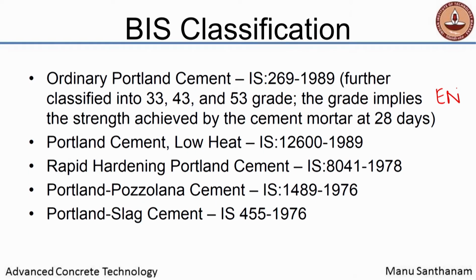Clay has aluminosilicates which are basically present in layers, and some clays have water between the layers. So, when you heat up to a certain temperature, the water in between the layers gets removed and the layers get activated. This is exactly what happens inside the cement kiln also. The temperatures at which that happens is nearly 700 to 900 degrees Celsius. At that level you produce calcined clay, and in the past the PPC used to allow up to 25% replacement of cement clinker by calcined clay to produce PPC.